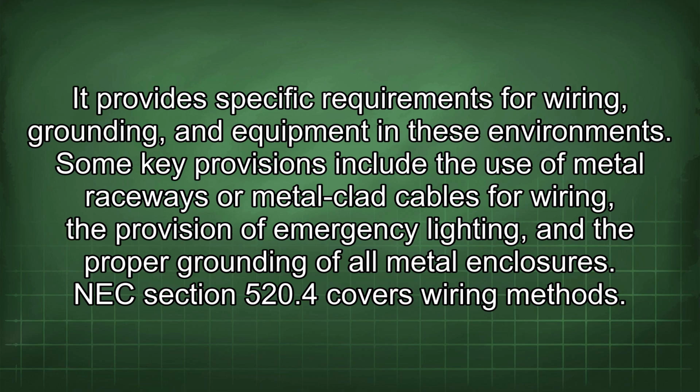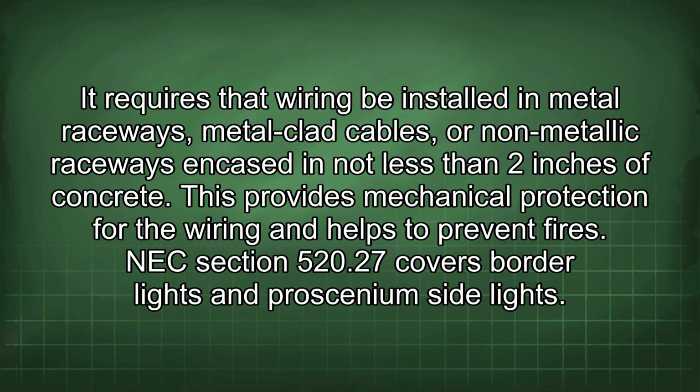NEC Section 520.4 covers wiring methods. It requires that wiring be installed in metal raceways, metal-clad cables, or non-metallic raceways encased in not less than 2 inches of concrete. This provides mechanical protection for the wiring and helps to prevent fires.